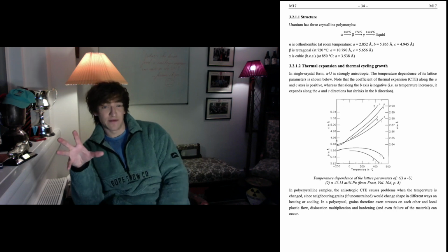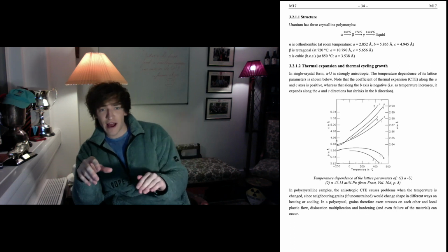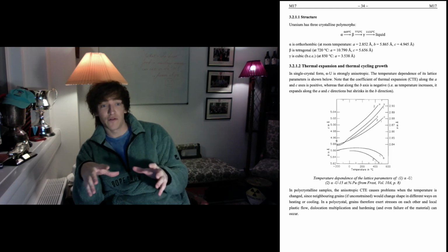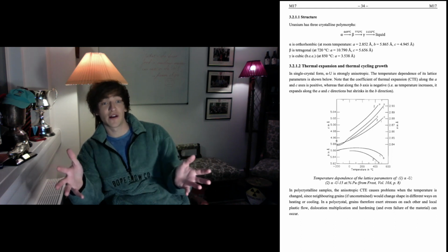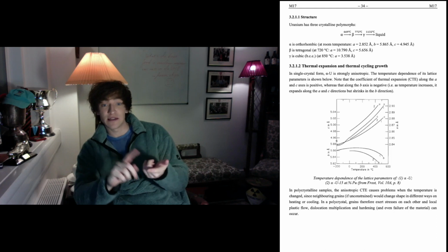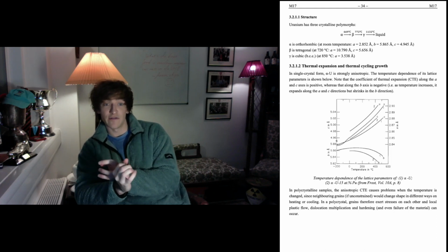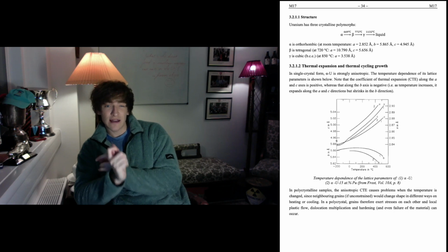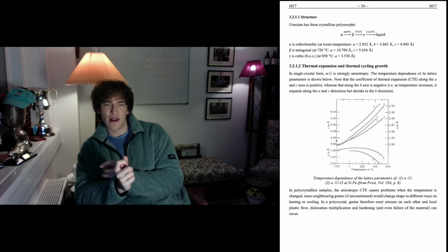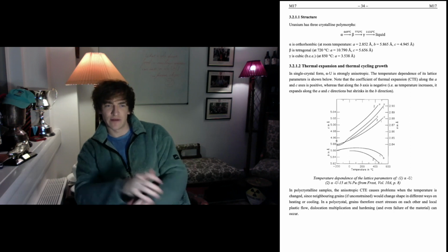Now this raises alarm bells, because if we're going to operate our fuels at high centerline temperatures, when we're starting up and shutting down our reactor for pure uranium, our fuel's going to go through all these phase transitions, changing dimensionally and exerting stresses on the cladding and the fuel itself. So let's take a look a little bit more into that. What happens to uranium as you change its temperature?